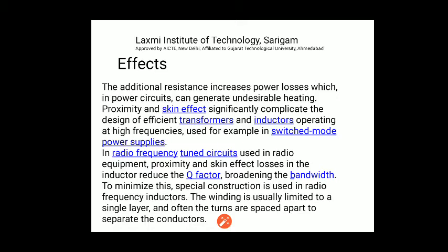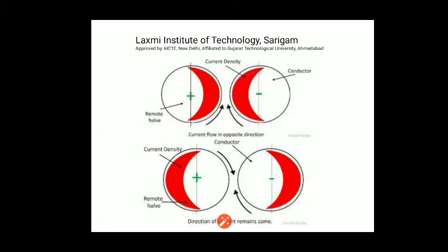To minimize this, special construction is used in radio frequency inductors. The windings are usually limited to a single layer, and often the turns are spaced apart to separate the conductors. Next we will discuss the diagram.